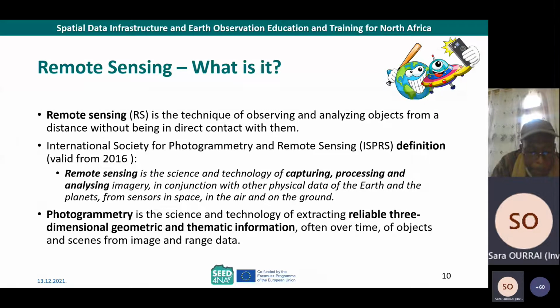So photogrammetry equals geometry, it's the most accurate, and when you need to do some accurate business, you need to produce a photogrammetry mission and a photogrammetry survey. No questions about that. But if the accuracy is not so mandatory, remote sensing is the science you can use to gather information about the Earth's surface. Remote sensing is mostly radiometry, and photogrammetry is geometry and accuracy.